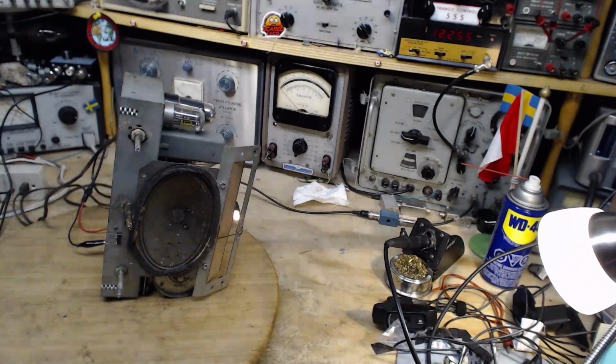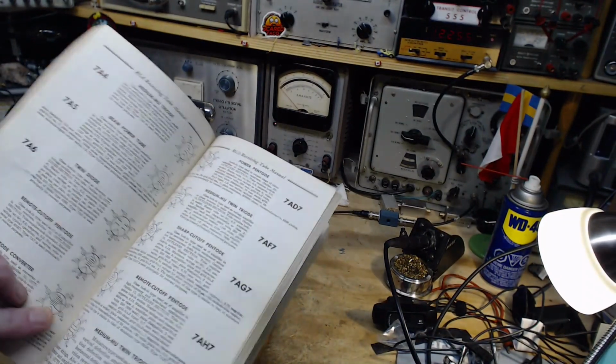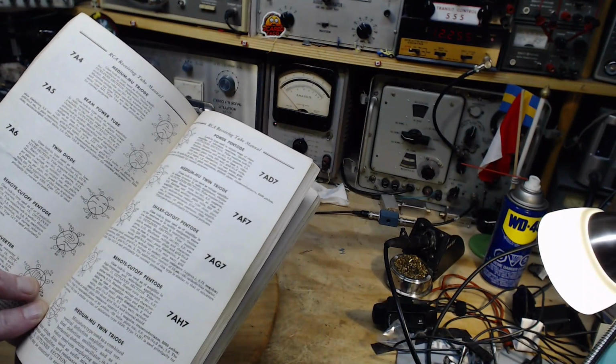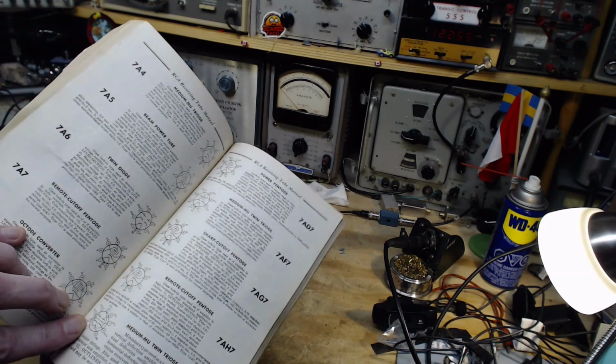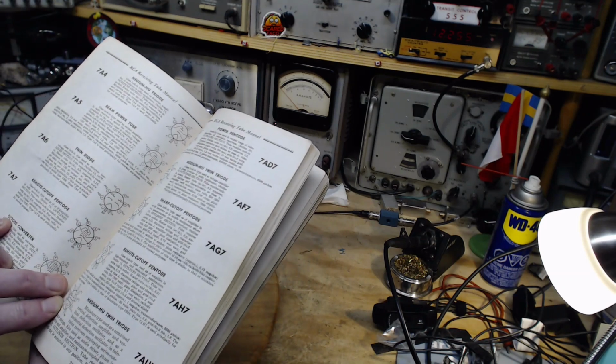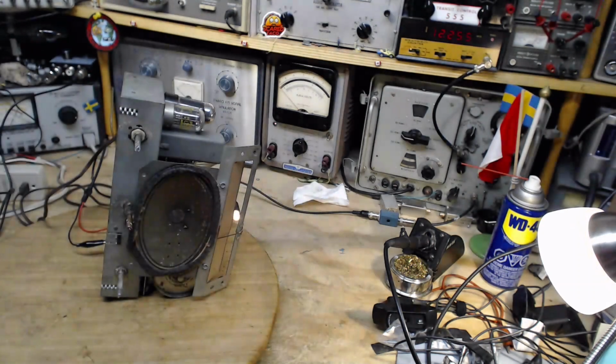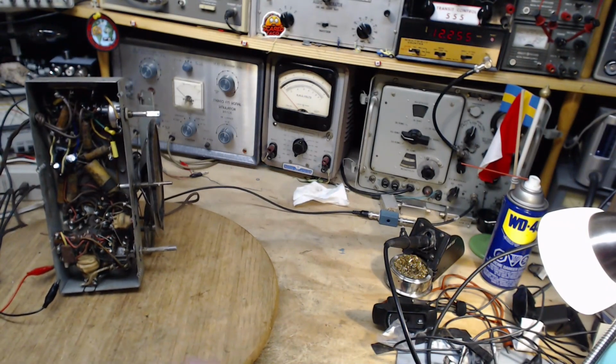The grid is pin number 5, I think. I'm going to double check. So it's grid number 4 that's being used in this tube. This is an octode. So grid 4 is pin 6. Wow, okay, I got 5 in my head. Good thing I checked. Pin 6. So we take a look under here